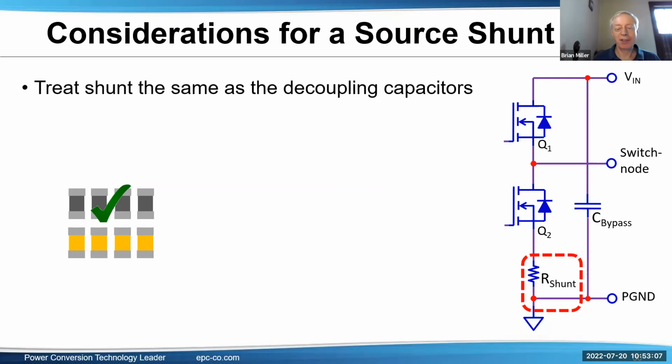For example, if it's a 5-volt gate driver and it rings up to say 5.5 or even 5 3/4, that's not bad. Keeping the turn off clean is probably more important. You don't want it to ring and potentially turn back on. So I prioritize turn off ringing over turn on ringing.